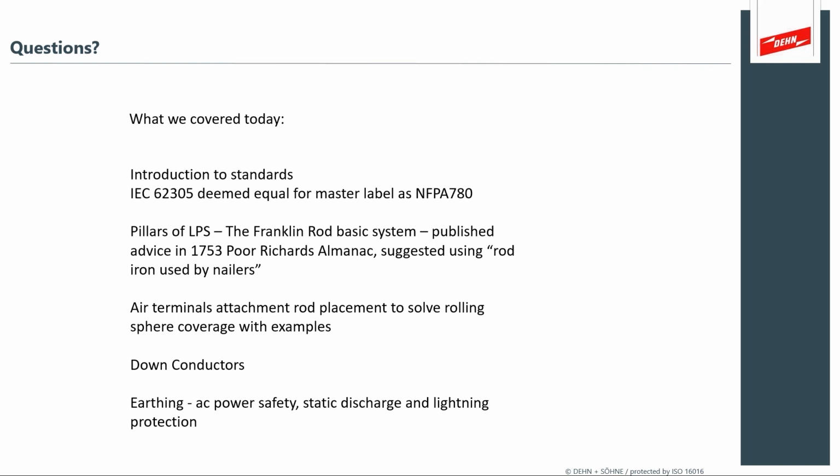What are you able to do? So if you can't keep it a meter away, you bond to it. And how do you know what's inside your wall is another big question. That's why you really want to make sure that everything's bonded. Okay? And that's where my good friend Stephen, that's that term, bond it. When in doubt, bond it.